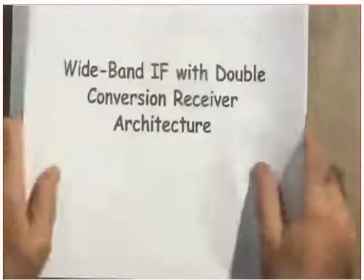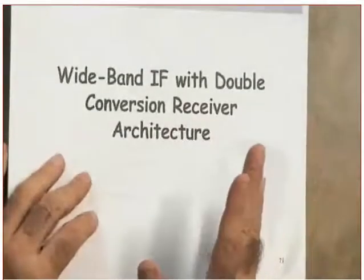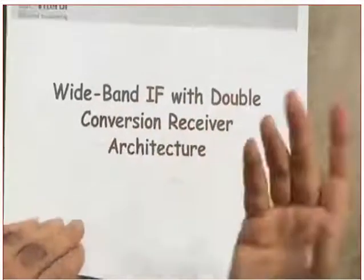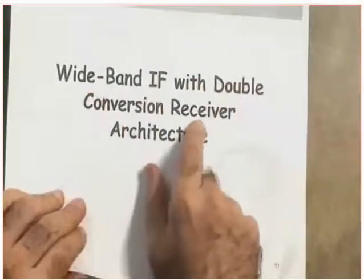Another type of receiver, by the way. In this class, I'm only going to hold you responsible for the superheterodyne and the zero IF. All of these are just showing it to you. Are you following? I'm just showing it to you. Another one is a wideband IF with double conversion receiver.